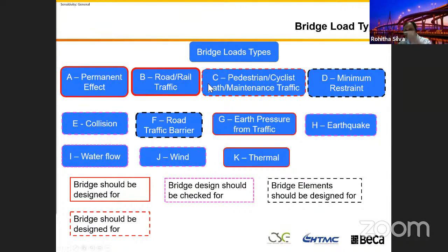The bridge design is not the combination and permutations. It's not that you run your, for example, the column design, you just run your interaction diagram and you push thousands of load cases and you say it's all inside the capacity curves, therefore it's working. It's not that. You just need to pick these 3 or 4 load cases, and you need to understand why did I get these 3-4 load cases and why these points are there. You should be able to justify whatever output you got from your analysis.